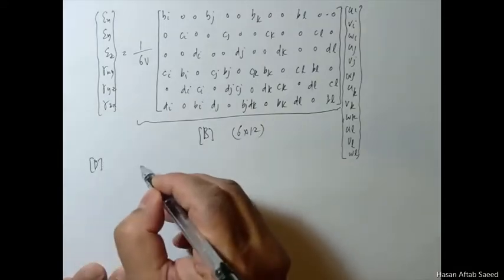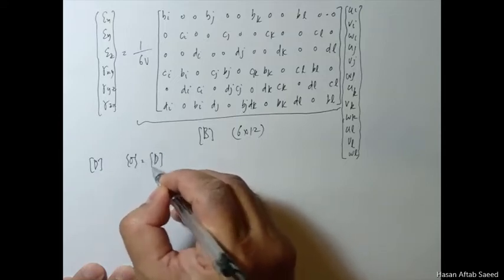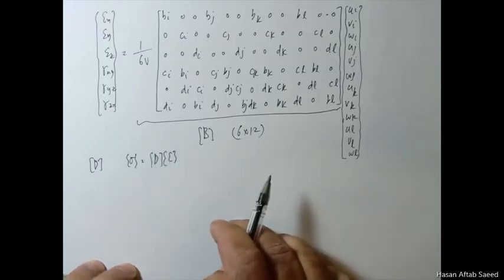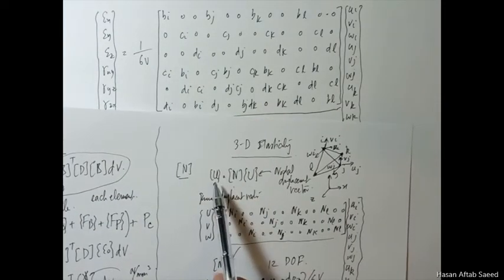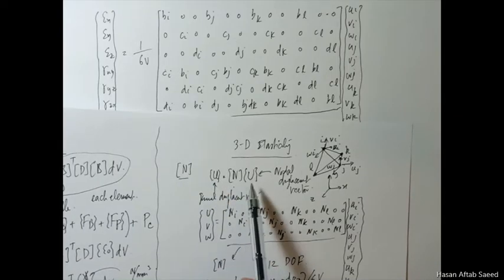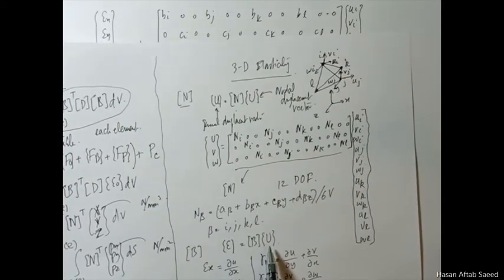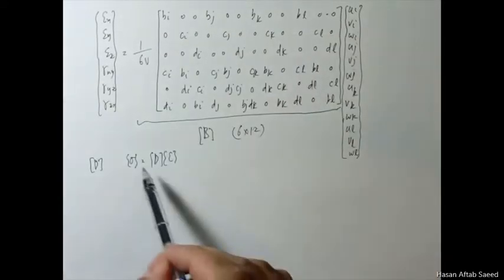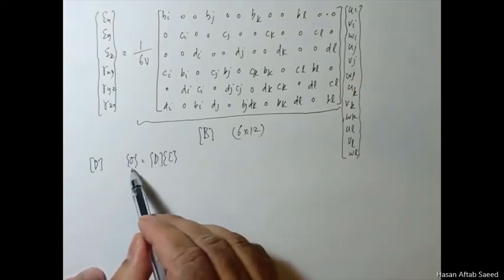Its application is that the stress and strain vectors are joined together, just like N linked the general expression of u with the nodal displacement, and B linked the strain vector with the nodal displacement vector. Here D links the stress vector with the strain vector.